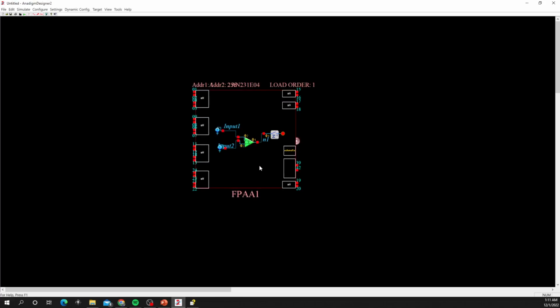And after that, okay, right now you pretty much have everything. You have the input, you also have the output. So the output is basically just simply input 1 plus input 2. And let's say you need, I would say, an oscilloscope to observe what's happening for the output. So you can simply go to simulate, create oscilloscope probe.